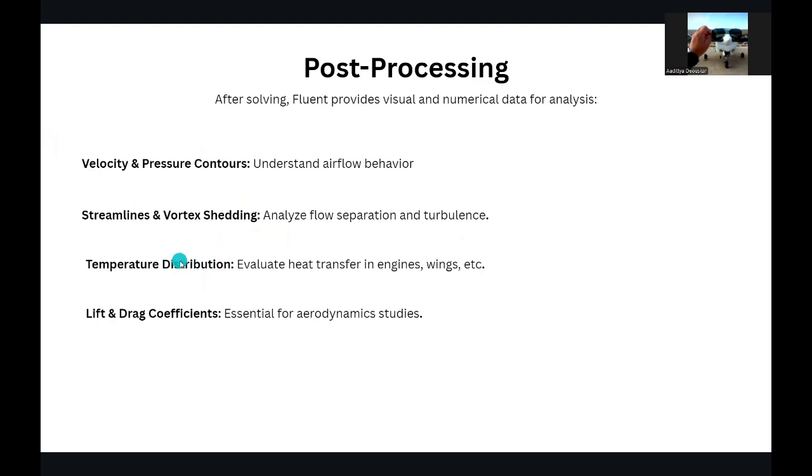Also in thermal simulations, we also get the temperature distribution. So this helps us to visually determine what is happening in the system. Also, for some numerical data, as it's mentioned here, lift and drag coefficients. Lift and drag coefficients vary geometry to geometry, and ANSYS helps us calculate them for every specific geometry. So also you could calculate the moment coefficient. Yeah, the lift force, the drag force, and the moment force as well.